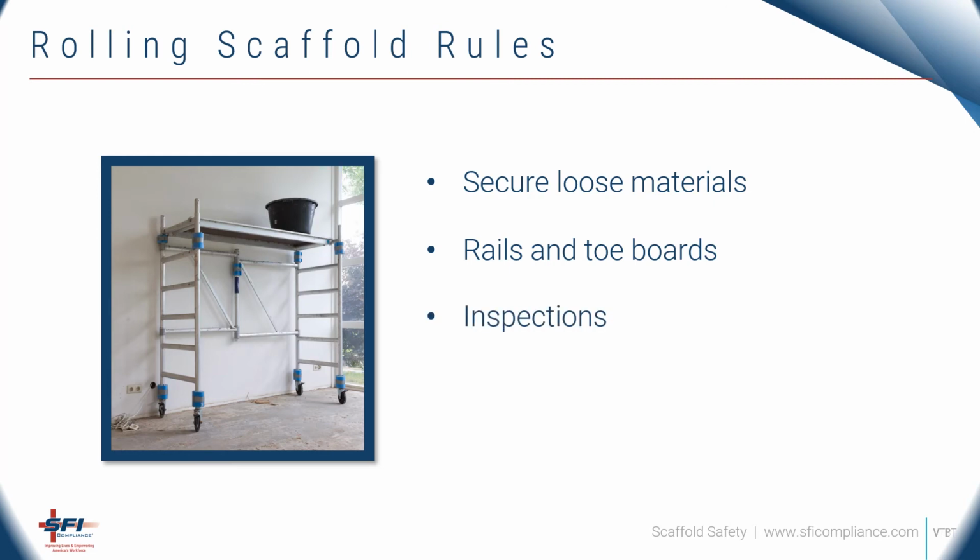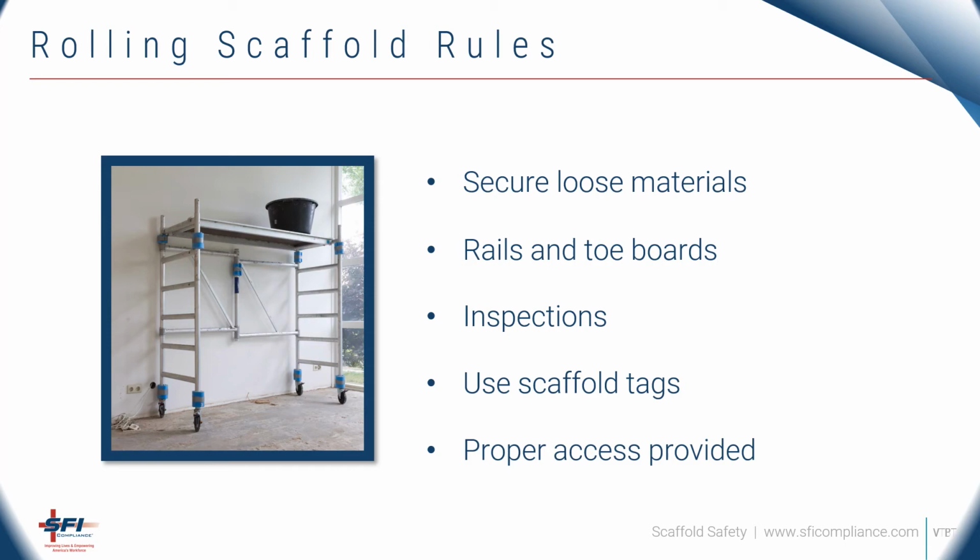All scaffold members must be inspected before each use. Damaged scaffold members must be removed from service immediately. Scaffolding shall be inspected by a competent person. Scaffold tags should be used by the competent person to mark scaffolds either safe or unsafe. Proper access must be provided and used for each scaffold.